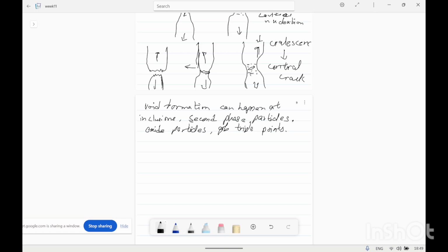So the fracture will also generate at the local shear bands, means the shearing is happening at the 45-degree angle from the tensile loading direction, and along this direction the voids start to form first.